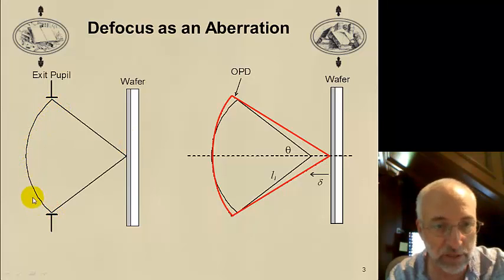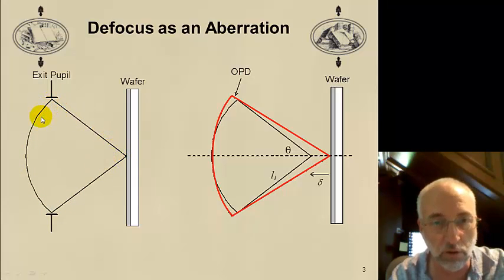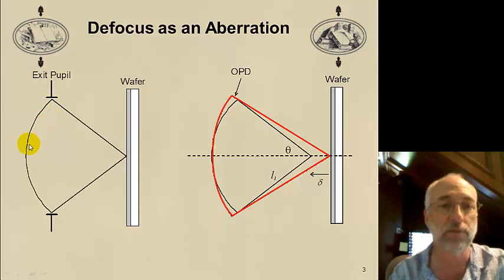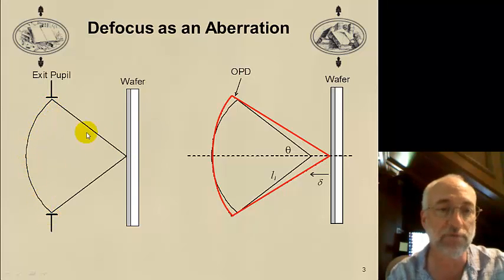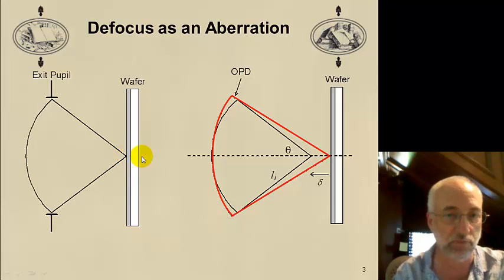that means there's a certain curvature of the wave of light that has the right radius of curvature, so that all the light from all of these different points on the wavefront will converge down to that wafer point in phase. So all of the points on the wavefront are in phase, and they all travel the same distance to get from this spherical wavefront down to the wafer, so they remain in phase when they combine at the wafer.